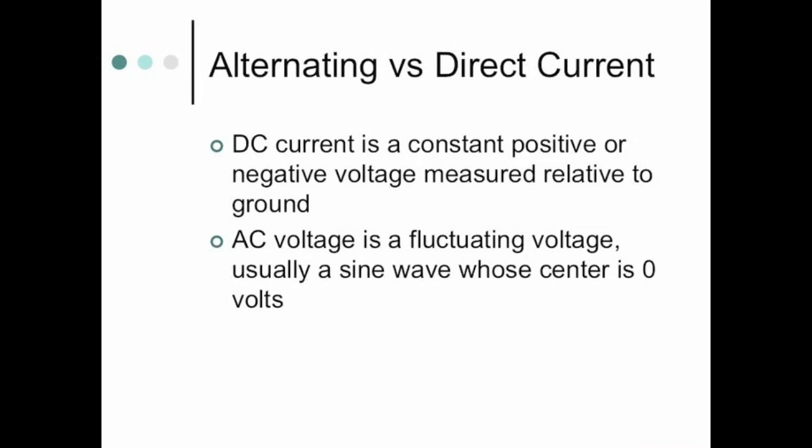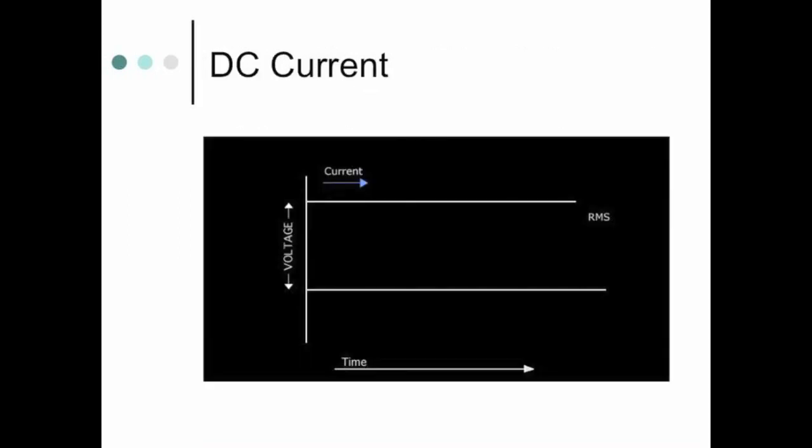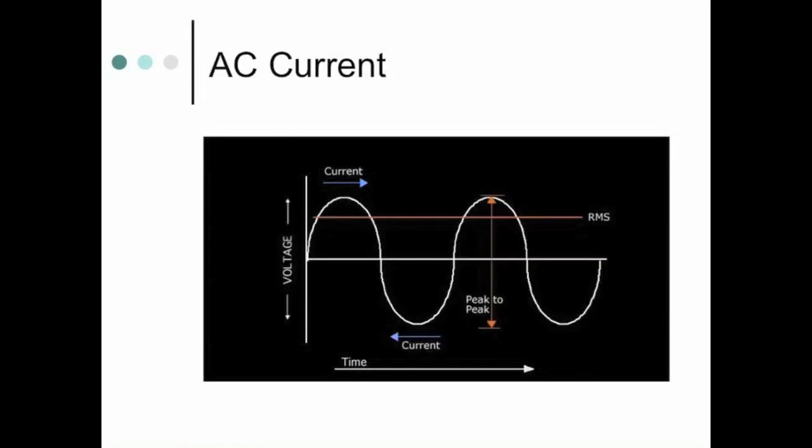Direct current, alternating current, AC and DC. Direct current is a positive potential that's a steady potential that doesn't deviate from its voltage. So what would be something that uses DC power? A battery, your iPhone, a flashlight, they use DC. AC is an alternating current that fluctuates around a center point. Let me give you a few little pictures. That's DC, so there's a steady voltage and a steady current. AC is an alternating current. So where is AC found? AC is found out of the plug in the wall. That's 110 volts AC. In other countries, it's 240 volts, 220 volts.